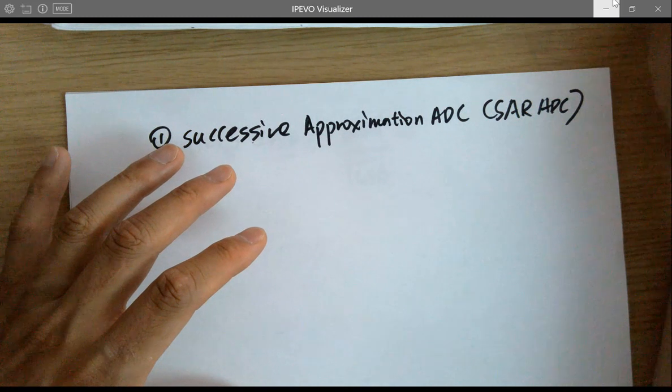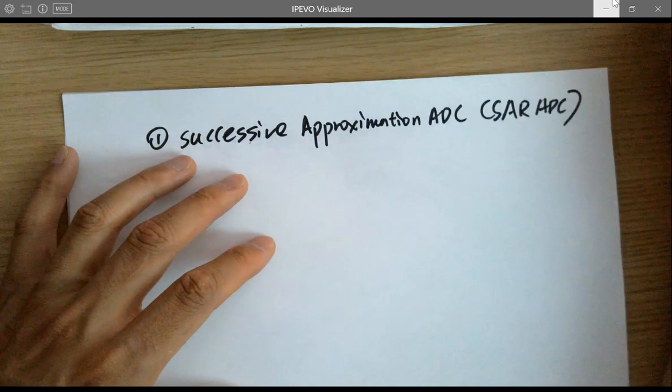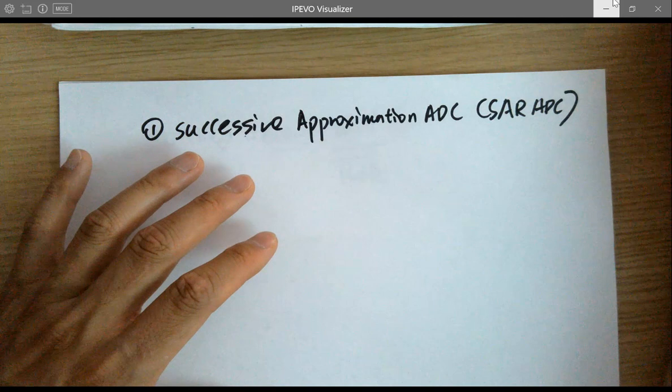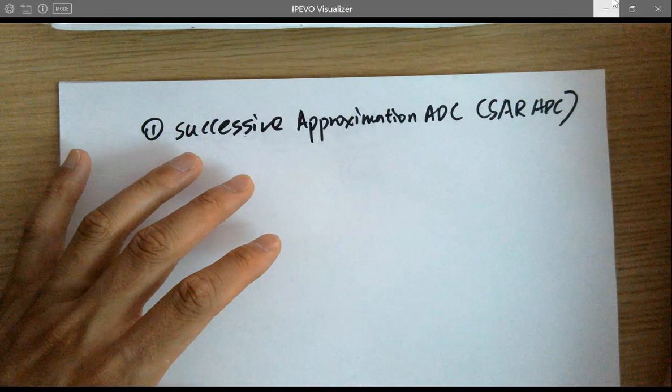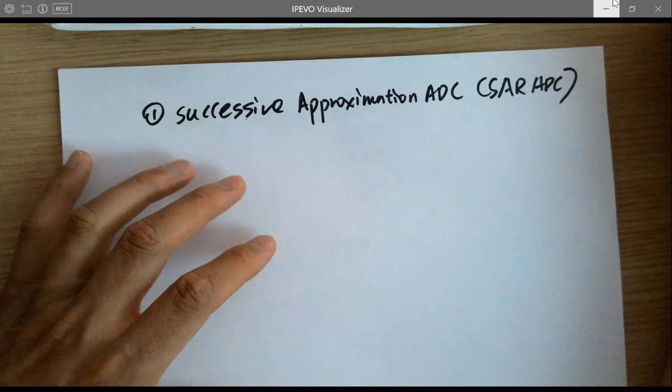It's all the A-something pins on the Arduino. Right behind it is a SAR ADC. So it's a 10-bit SAR ADC being used for Arduinos.